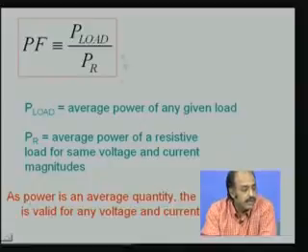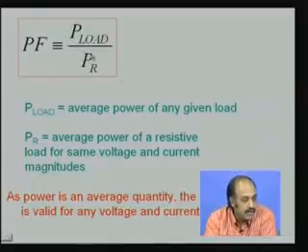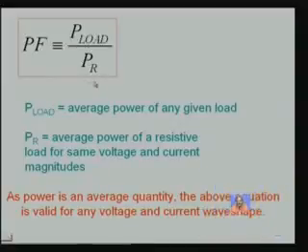And it should be noted here that the powers are calculated by using integrals. Integral of a waveform is basically the area under the curve. So, it is actually immaterial whether the shape of the waveform is sinusoidal or any other arbitrary wave shape. The power values that we get here do not depend upon wave shape. So, whatever may be the wave shape, this definition is valid, PF which is equal to P load by PR.